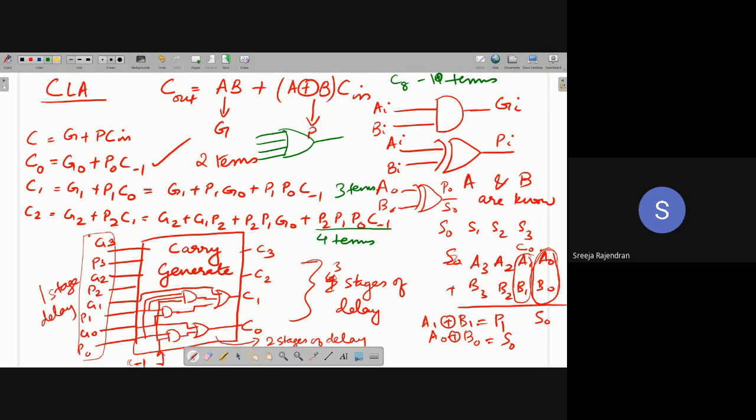And that is also something that the manufacturer mentions in the data sheet. So I can have a maximum of 3 inputs to a gate or a maximum of 4 inputs to a gate. So why can't I go beyond this? That maximum number of inputs that can be applied to a gate, we have a term for that. It is called fan-in. This is the fan-in of a particular logic gate.